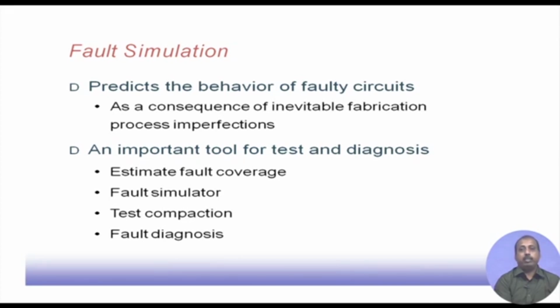It may so happen that some test has failed, in the sense that we applied some pattern to a circuit, in simulation or at the manufacturing stage, and we see that the fabricated chip has failed that test. But why has it failed? From the faulty response, we should be able to trace back and see where exactly the fault is.